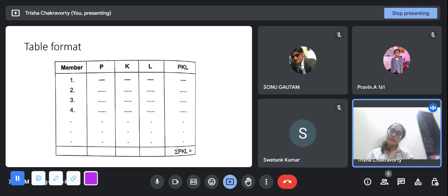So Young's modulus will remain the same for all the members. They're almost 99% sure, but the cross sectional area may vary. Like suppose in a truss, for example, in a bridge, you know the kind of loading that is going to come before you even analyze it. So you can anticipate that in certain members the force developed will be greater, and you know that stress is force by area, right?